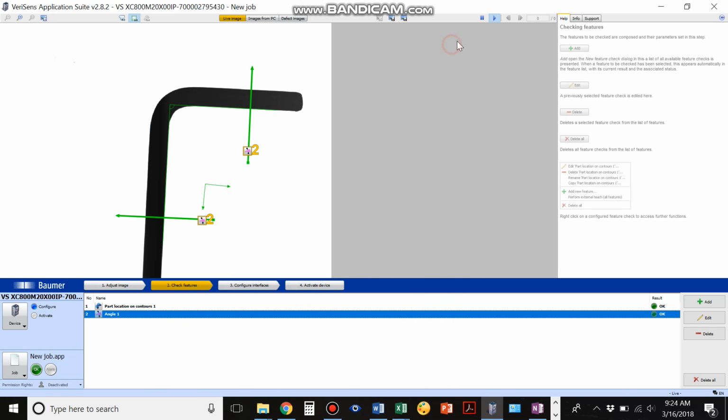Okay, today we're looking at an application for a customer. These are bent metal parts, and we're looking for the angle here in this bend. These parts are pretty small, so the setup we have currently is a backlight underneath the part, shining light up, and a camera looking straight down. This setup really creates a nice silhouette here. As you can see, it creates nice edges, nice contrast.